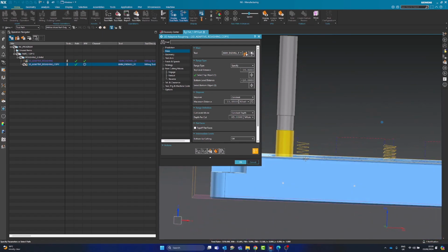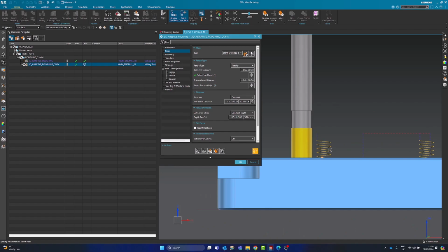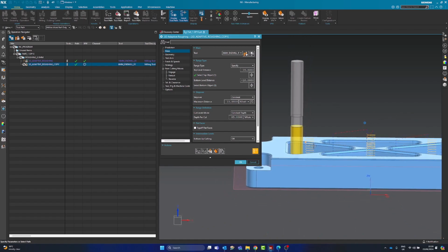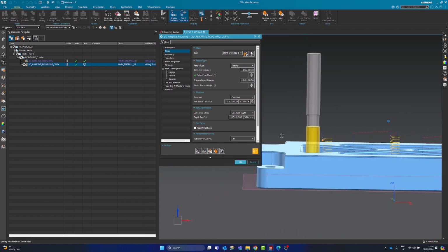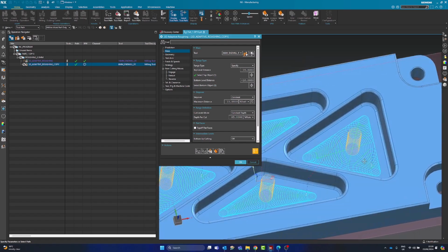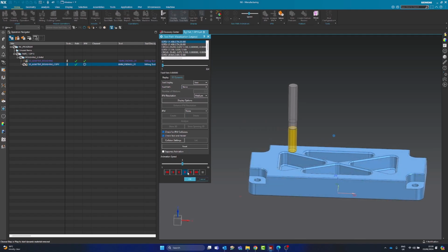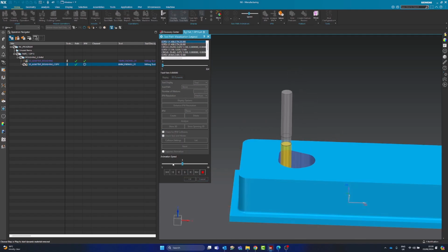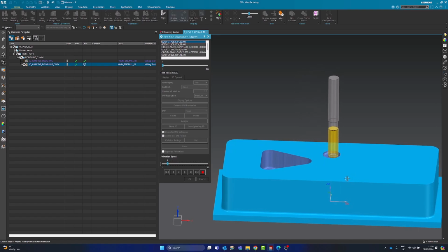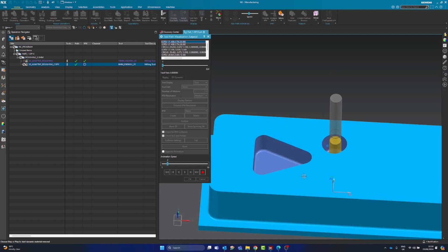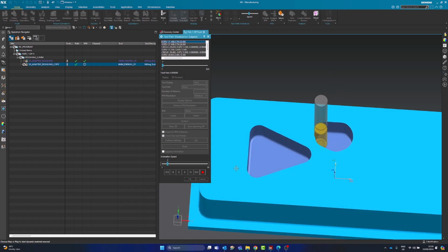And you can see this helical engage is 3 mil above. Or it actually looks a little bit more. But this is the kind of toolpath we want. So if we just verify this, and we'll see what we've got. So 3D dynamic, and we'll slow that down a bit. It was a bit fast, wasn't it? So you'll see the helical engage in like that. You see these nice moves, and you see how it cuts and comes across. These are the low height transfers I was talking about.